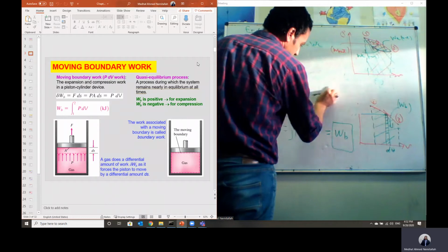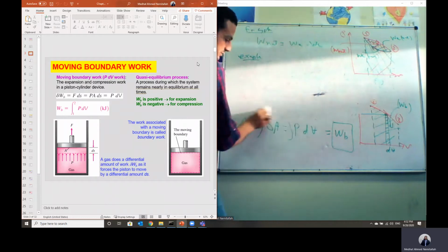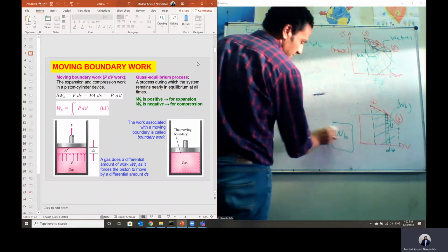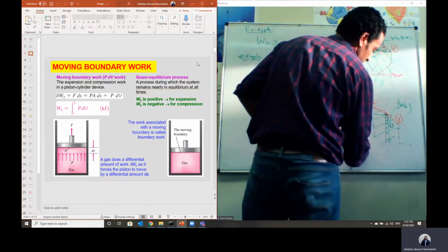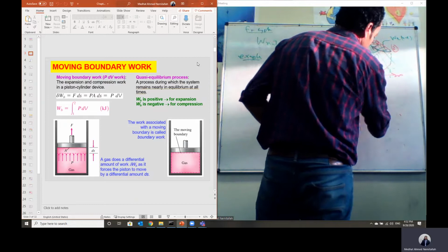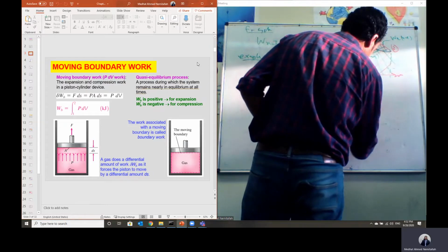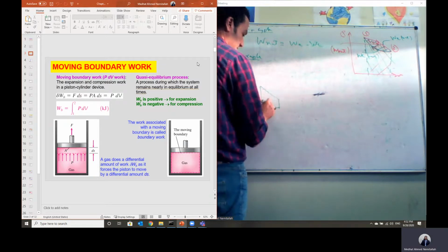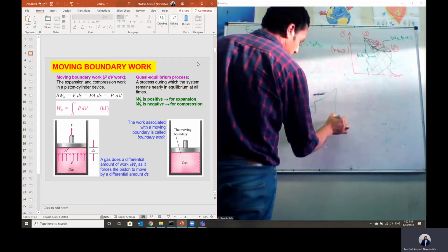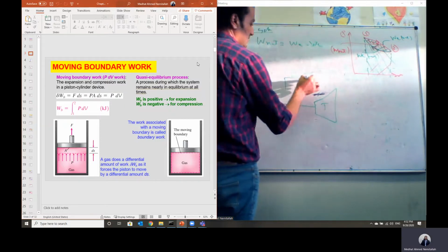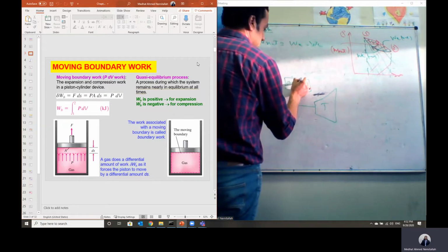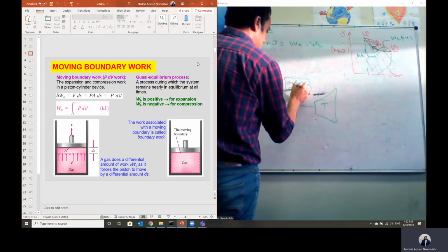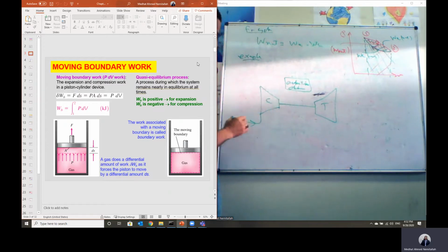I think you know about the hydraulic turbine, when we have water at high level coming and hitting the blades of the turbine, then it can generate work. We have another kind of turbine which we call the gas turbine. The gas turbine consists of a compressor. This compressor is connected by a shaft to a turbine, and in between we have a combustion chamber. This combustion chamber takes the air coming from the compressor. So atmospheric air comes to the compressor at atmospheric pressure.